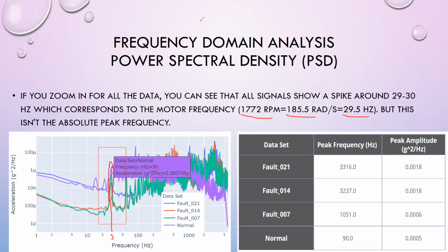So it's very important, for example, in the system with normal bearing, if this speed shifts to about 90 hertz instead of 30 hertz, we will have the resonance. And in your motor, you will hear a lot of noises which show that your system is about to reach the resonance phenomenon.